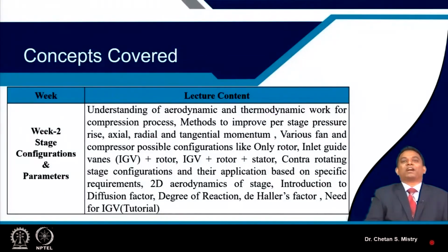We were discussing improving pressure rise by increasing peripheral speed, increasing axial velocity, and increasing deflection angle, and what the limitations of those concepts are.